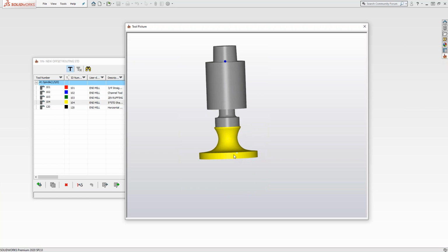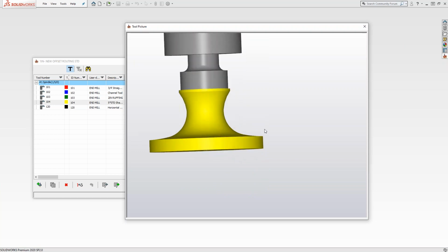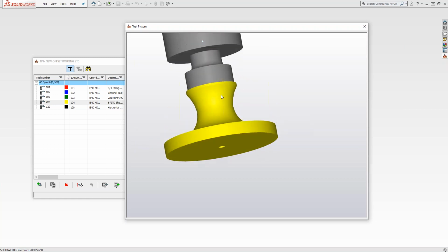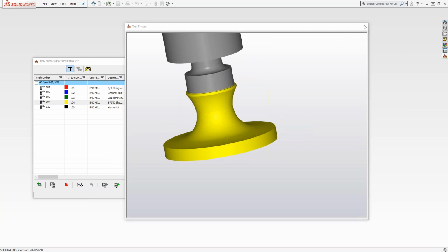And the way we defined it in the 5-axis toolpath is, instead of the bottom corner being right there, he actually defined it to this point right here. Because in 5-axis, as you probably have seen, it's surface-based. So that bottom edge of that surface was the contour he chose in his parallel to curve 5-axis toolpath, and he told the tool to follow this point right here along that curve, and it formed that shape as it went in 5-axis. So really complex stuff you can build simply by just letting the geometry do the work for you.